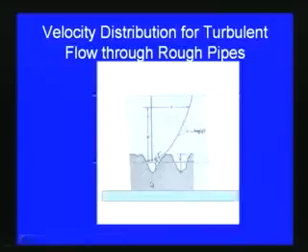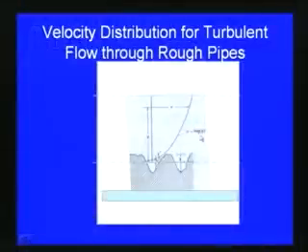So this is the general pattern, which we have now shown through experiments, as derived by Nikuradse, or through theoretical development, or the various relationships. The laminar sublayer, we either approximate with respect to a power law, or we consider a linear variation in the laminar sublayer, and then beyond that we consider the variation with respect to the logarithmic law. So this, both theoretically as well as experimentally, we can show.